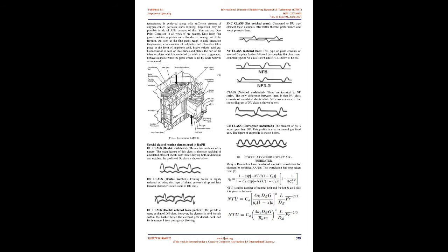The process in which heat is transferred between hot and cold fluid in a continuous process is called recuperative. In this there are the tubular type air preheater and the plate type air preheater. In the regenerative type preheater, there is also an exchange of heat between the hot and cold fluid, but it is not continuous.